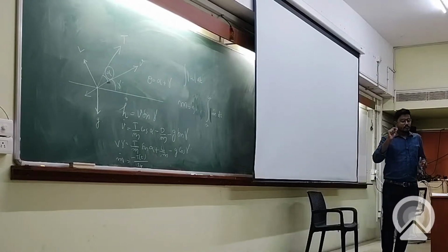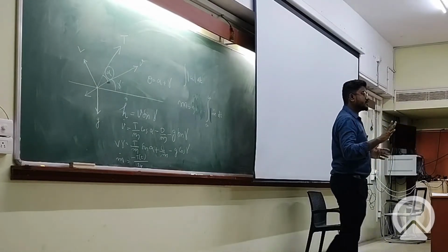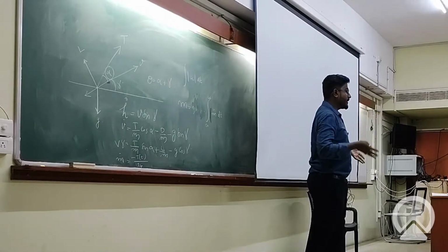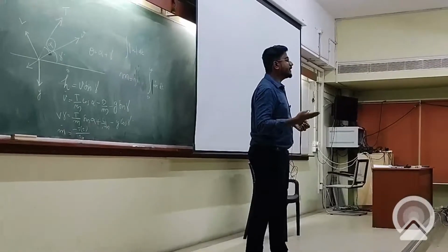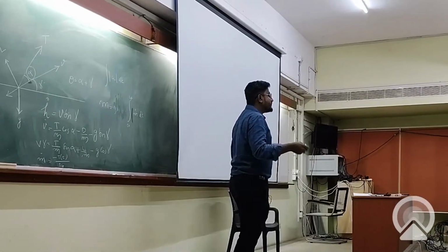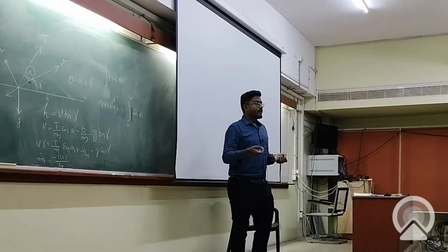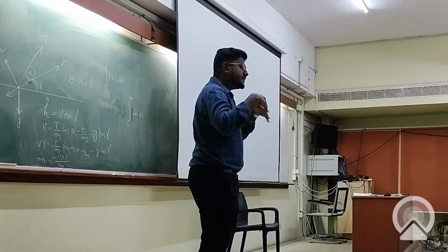What is the velocity achieved by a spacecraft in a low orbit? It is of the order of 7.5 kilometers a second, for a circular orbit, root of mu by r. But actually, you are delivering 9 kilometers per second. Where does this 1.5 kilometers per second go? It is actually going towards losses.